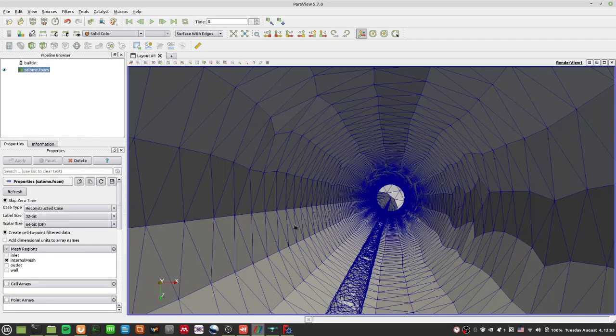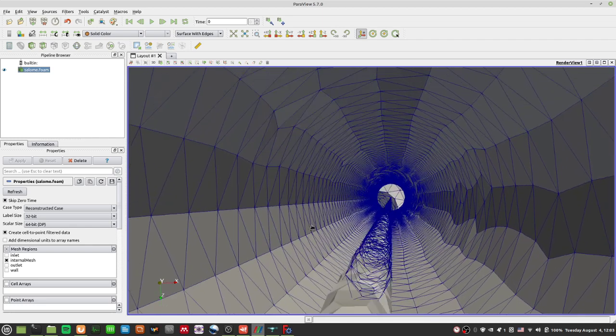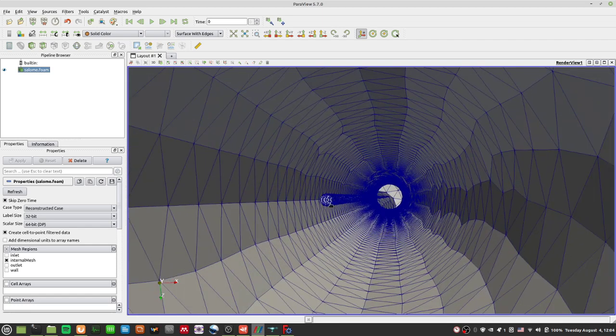So in summary, what actually happened? There was this little extra shape here that actually required a way finer mesh to resolve, and that's also why you had this intersecting triangles problem. The intersecting triangles problem was made by an overly coarse mesh due to this little circle thing in the center.